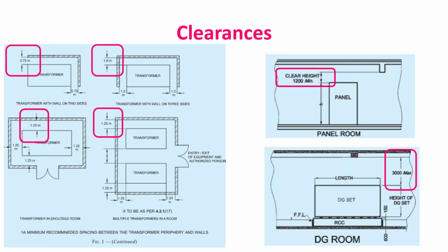Yes, now you must appreciate that this particular building may be subjected to wind loads, may be subjected to seismic loads. So obviously it should have some type of an anchorage. So what our code specifies, this is what they say. All foundations shall extend to a depth of at least 500 millimeters below natural ground level, irrespective of the strata. He's not talking about strata. So 500 is the minimum. So in case somebody was saying 300, please correct yourself. It is 500 millimeters.